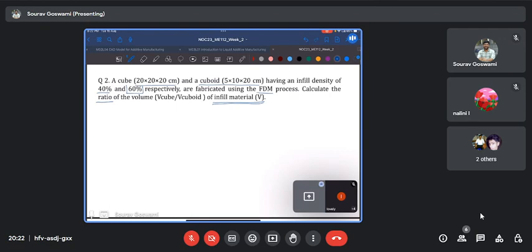So what does this infill density actually mean? Say you have a cross section or a contour. So as we discussed, it will be filled by certain strategies. Say you will have 2 or 3 perimeter contours, and then you will raster it depending on the angle with the x-axis.